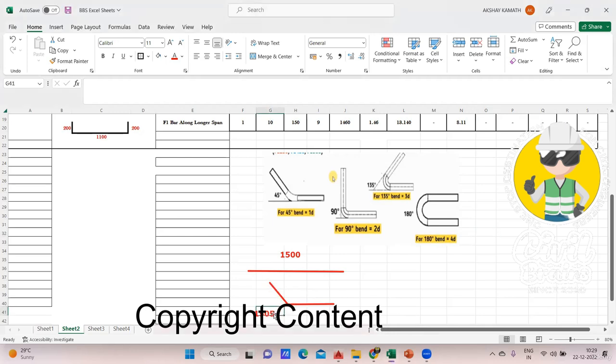Let me write this as an 8 diameter bar. Consider that the bar I have considered is an 8 mm bar. This length increased to 1508 mm. So what has happened? Actually, the length was 1500. Due to the bending, the bar has increased in length. But we want to deduct this extra length which has increased. This extra length we have to deduct.